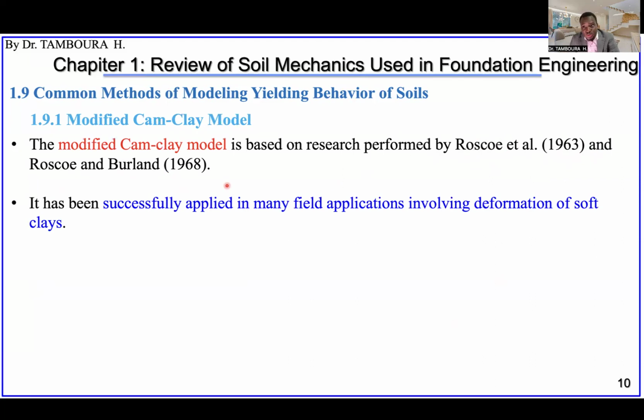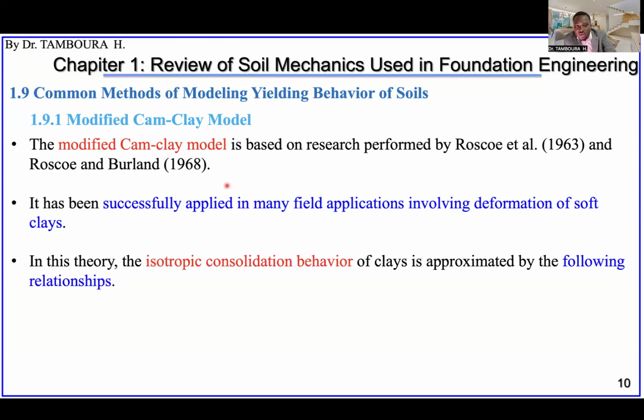Okay, so it has been successfully applied in many field applications involving deformation of soft clay. But you need to remember that this is for clay, okay? The name is even very clear. Clay, in the name there is clay inside. So modified CAM clay model. And in this theory, isotropic consolidation behavior of clay is approximated by the following relationship.